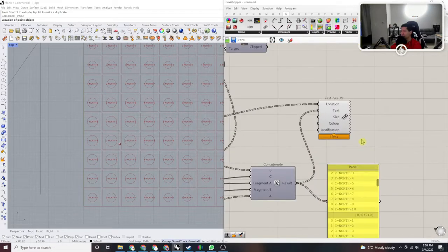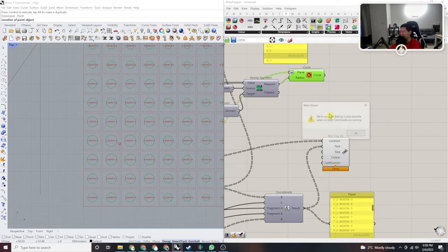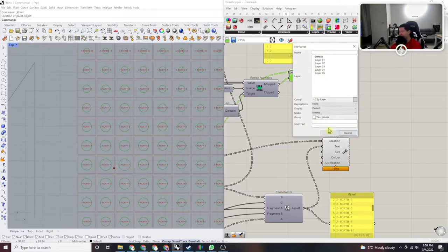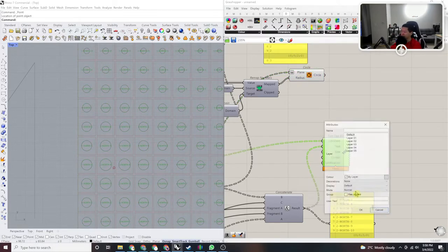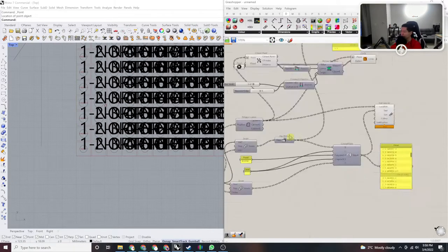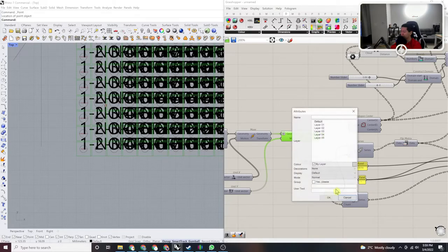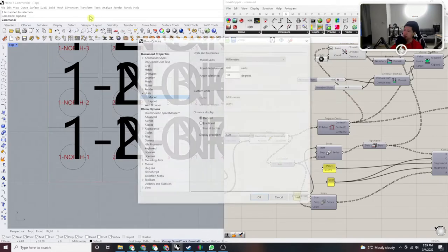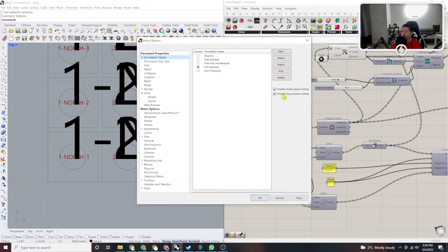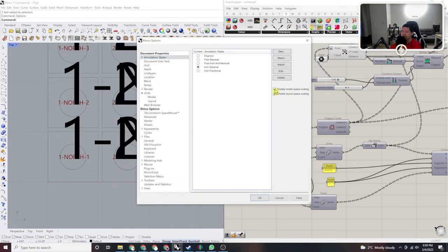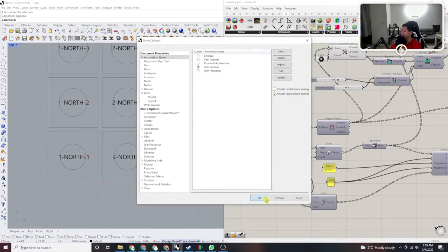Okay, and then once you have that, you can bake it. Oh, what's running right now? Oh, point. You can bake it. We bake this. And if you have this issue, I can show you how to fix that. So we got a bake here. Okay, so we see this text and we're like, oh, that's pretty big. So we want to go to options, you go to annotation styles, and disable model space scaling, and they'll return to how it's supposed to be.